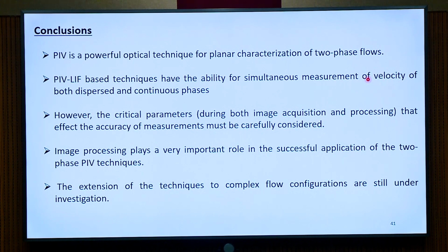So these are the conclusions. PIV is a powerful optical technique for planar characterization of two-phase flows. PIV LIF based techniques have the ability to measure both phases simultaneously. However, one of the drawbacks is that we don't have information about the particle size. So if you have a broad particle size distribution, then we will need knowledge of the particle size as well as the particle velocity.